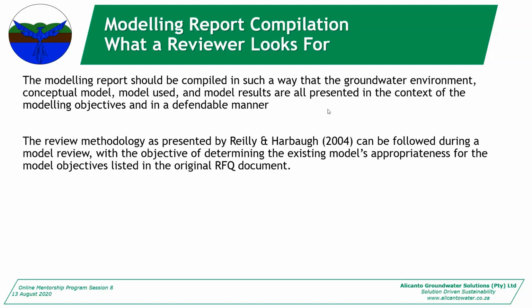Yeah, the review methodology that I use for my model reviews is by Riley and Harbach in 2004. It's an old paper, but it's still applicable, and you can follow this during your model review. The objective of your review is to determine the model's appropriateness for the model objectives listed in your original RFQ or your original discussion with the client. So how did your model fare against what the client wanted? If you wanted a contaminant plume and you gave him a dewatering cone, you didn't do that well.